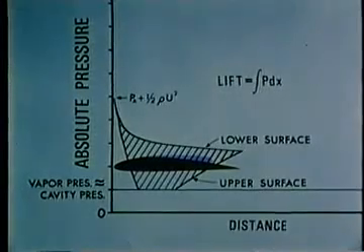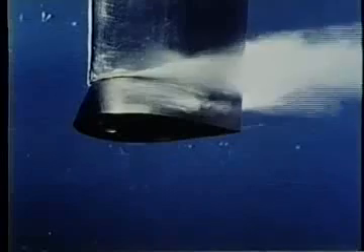Thus, hydrofoils, and for the same reasons, many hydraulic machines which are designed for efficient subcavitating operation lose efficiency when cavitating. Where cavitation is unavoidable, and conditions are such that supercavitating flow can be assured, it is possible to use supercavitating hydrofoil profiles specifically designed to achieve high lift-drag ratios.